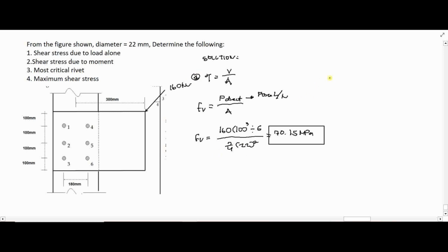So we have our formula for the shear stress due to torsion. That's the shear stress equals the moment times rho over J. This is the torsional shear stress, J is the polar moment of inertia, rho is the radius, and this one is the moment. So we can solve for the moment. That's M equals P times d, which we can solve for.